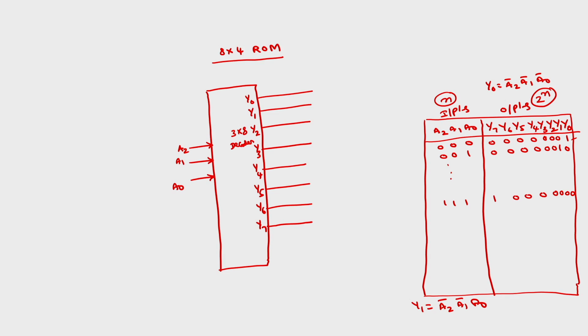Okay. And sometimes we can have some enable signal also. So suppose I want to disable this entire decoder itself. Here there is no option, at any time only one of the outputs is selected. So for that I will make one signal such that the output will be 0, none of the outputs will be selected. That you can call the enable signal. Okay. That I will discuss later. So this is about the basic 3 by 8 decoder.